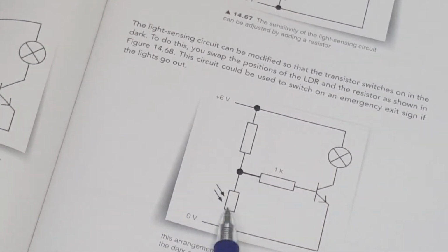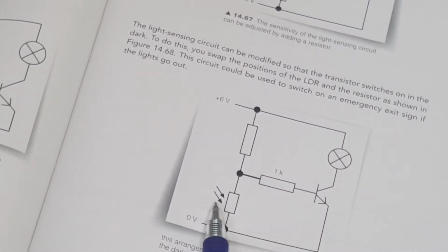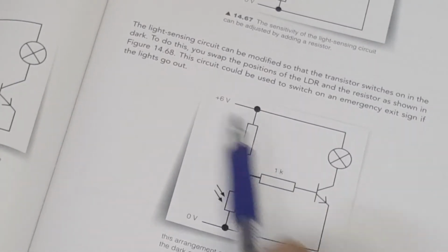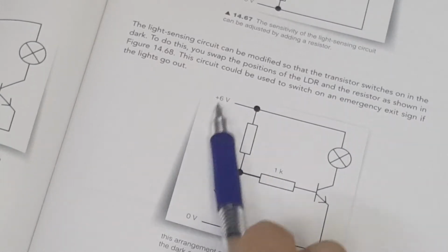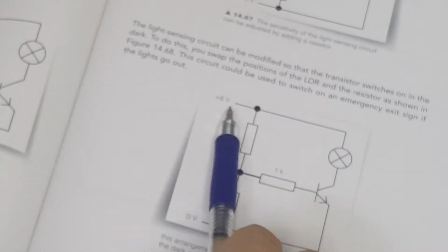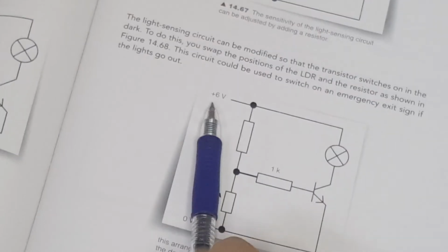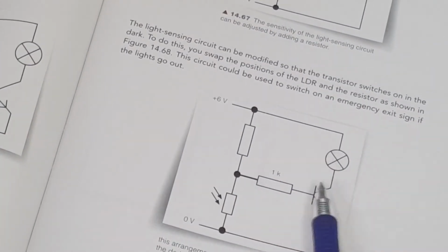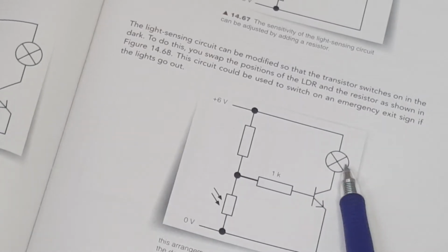So in this condition, when there's no light, the resistance of the LDR is very high. It behaves like an open switch, open circuit here. So the current will basically pass through here. All right. So the current I'm talking about is the current from your 6-volt power supply. And therefore, when it's dark in this configuration, the transistor is turned on and the lamp is turned on in